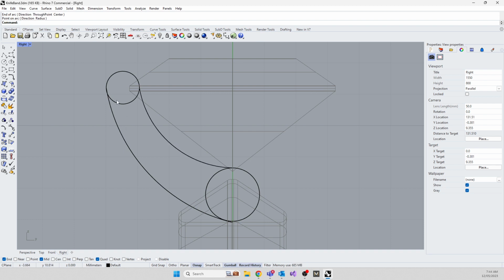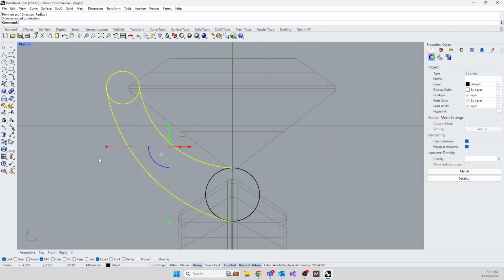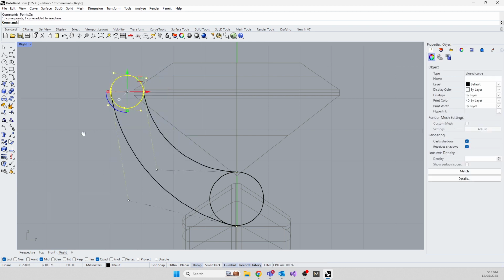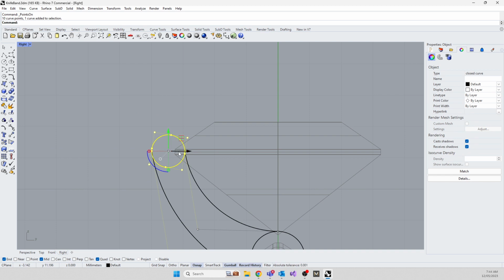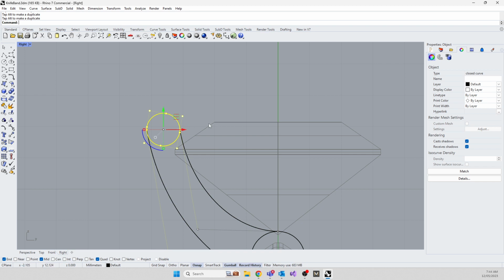Then I'm going to turn on the edit points for all these guys and pull them up a little bit. The reason I'm pulling them up is the setter is not going to say thank you for giving him a thing at the finished size. The setter needs a little bit of metal so he can actually set the job. The setter is going to take this component and push it over the stone. So always give yourself, for the manufacturing model, at least a little bit higher than the top of the table of the stone. Bring the prong higher than the table at a bare minimum, and some setters, like our setter, want even a bit more than that to give him leverage.